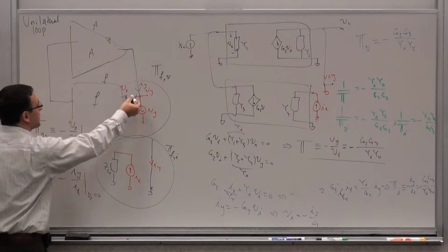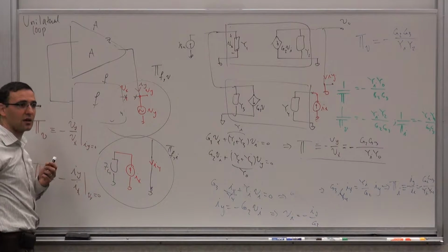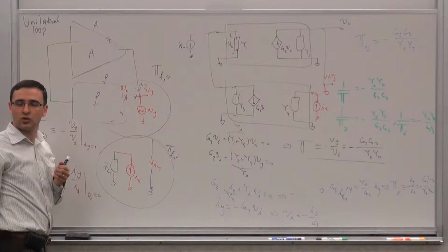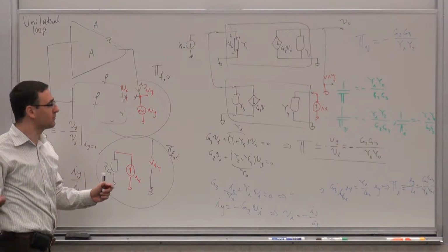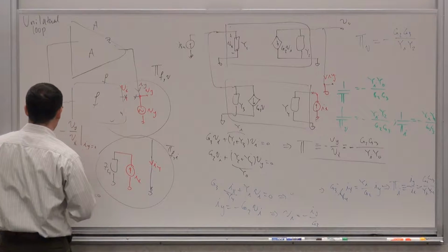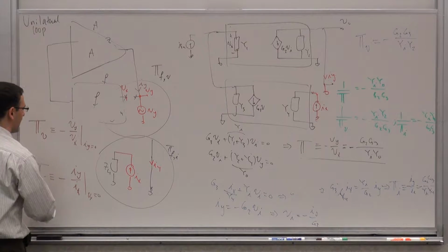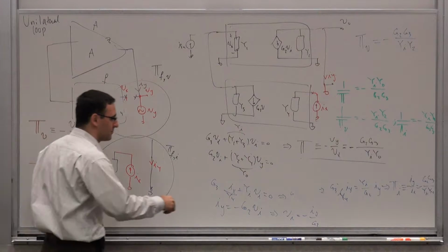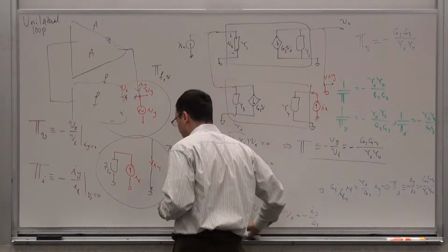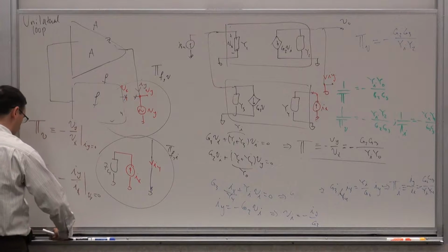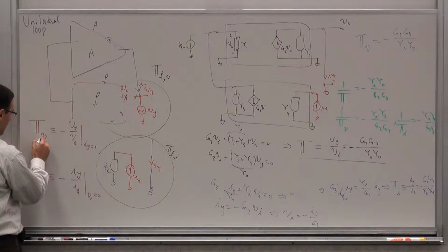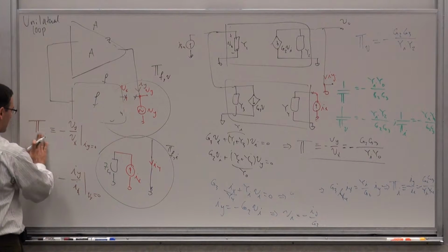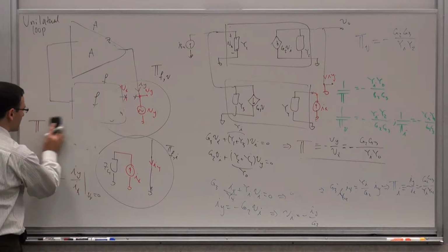Because now the signal can travel backwards in these two boxes and come back. So in general, I have both directions of signal flowing. Then, based on that, I can determine a reverse loop gain, which would be a modification of what we had for forward. Before, this was the forward loop gain; now I can determine the reverse voltage loop gain. Well, let's do it.